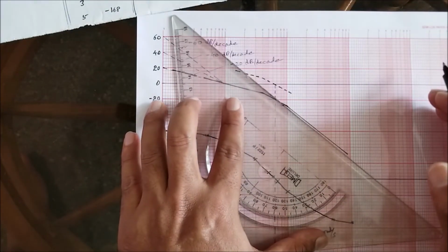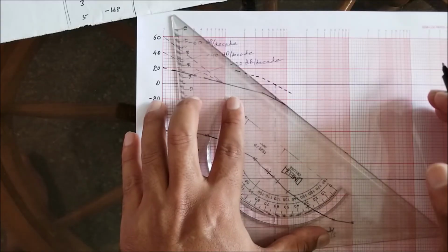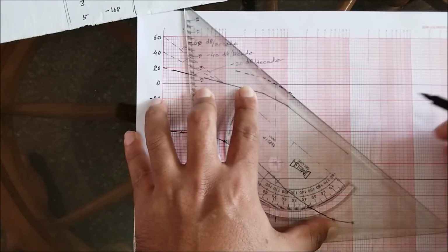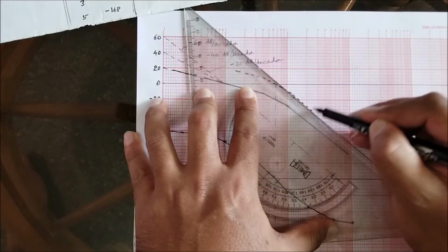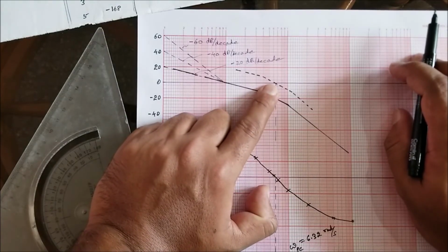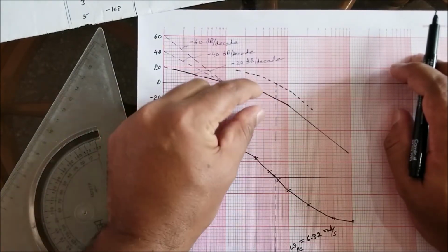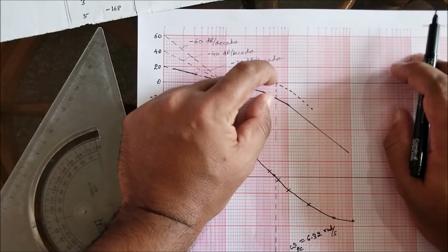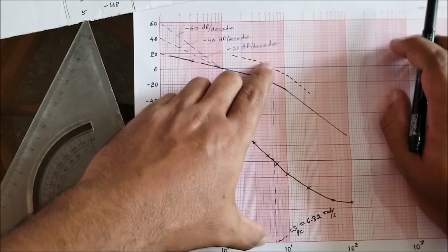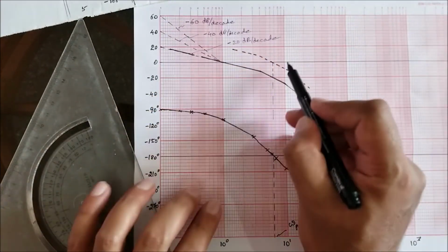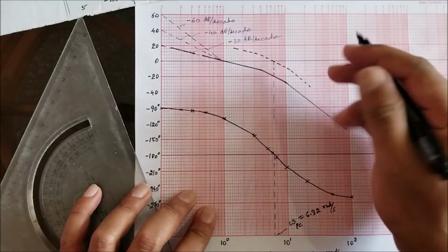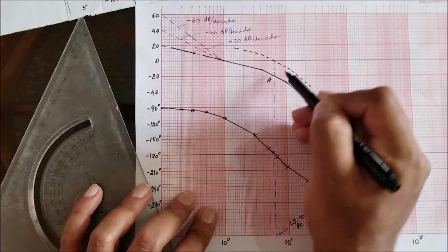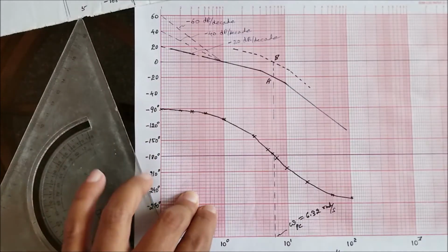So this is the shift which I required, parallel to minus 20, minus 40, minus 60. If it shifts like this, then I would have got the gain crossover frequency as 6.32, correct? Now this shift is required for marginal stability. If this shift is attained, then the gain crossover frequency will be equal to the phase crossover frequency. Now how much shift is required? Gain margin, correct? So that shift is nothing but the gain margin. Find it out. A to B shift is required for marginal stability, correct?